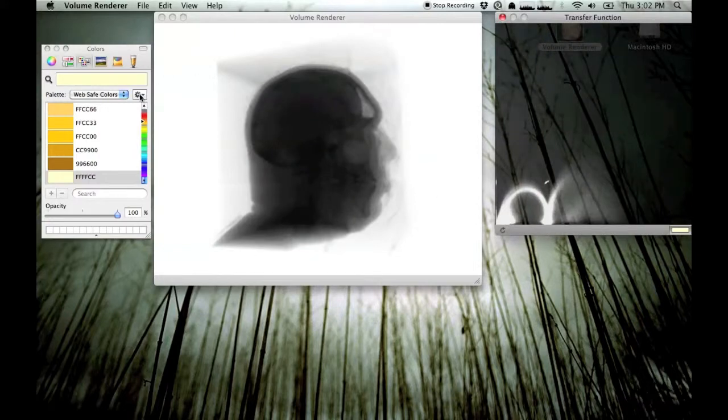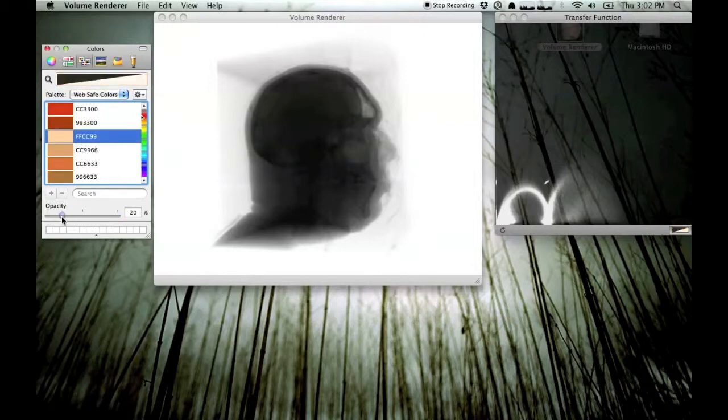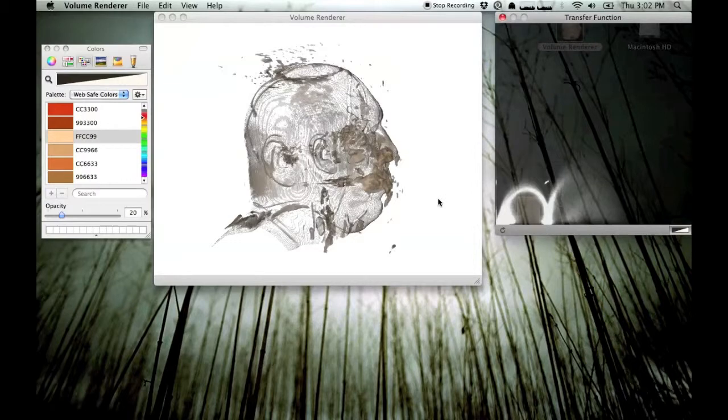Now we will reset the transfer function and build a new two-dimensional transfer function that will highlight the renderer's abilities to show materials of similar densities with different colors. Utilizing the cues provided by the 2D volume histogram, we can determine where the most prevalent gradient changes occur within a volume at a particular density. This visual cue defines a boundary between materials of similar density.